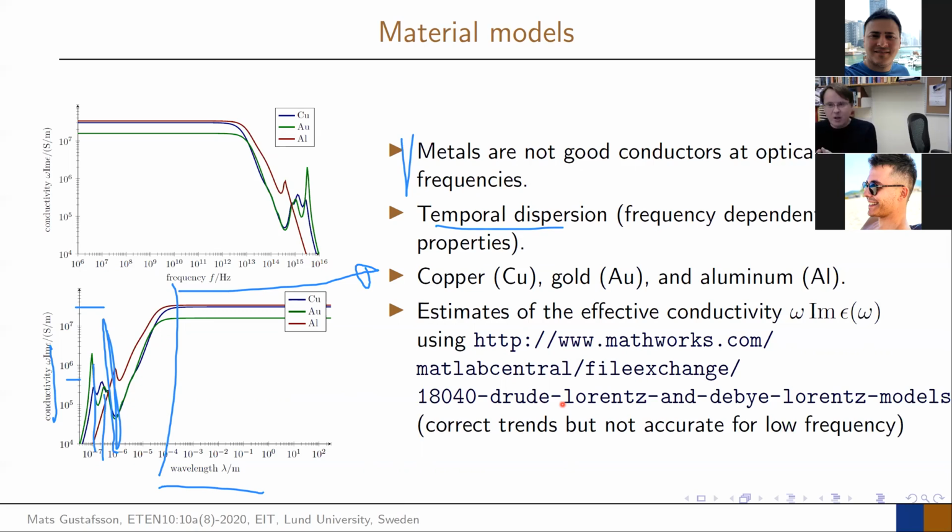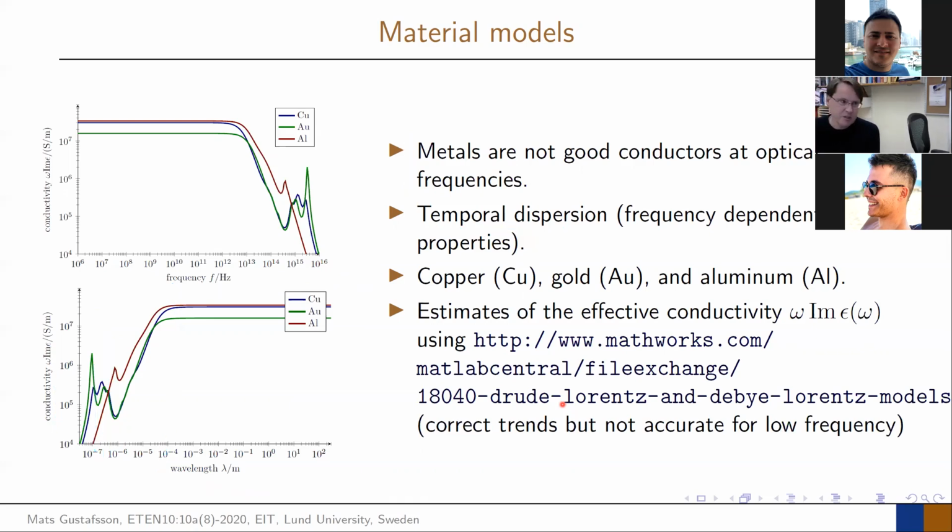And that kills one of the principles that I've taught you in this course, that when you look at antennas, you don't have to care about the specific wavelength or frequency. You just compare the size of your antenna with the wavelength. We measure the dipole as a half wavelength dipole, we say how long it is compared to the wavelength. That doesn't work anymore when we go to these optical structures, because the dispersion is so strong. The dependence of these materials on frequency is too high to do that in some ways. So that starts changing a lot of things in the design.